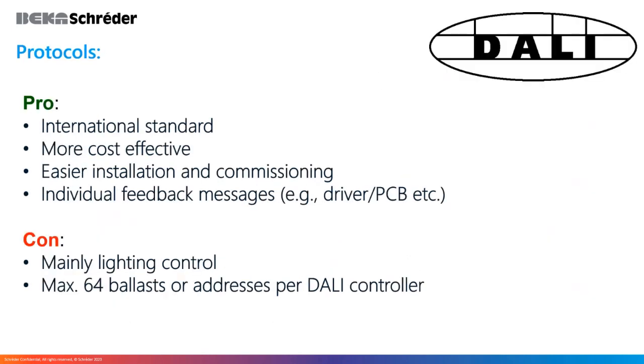Just some general pros and cons. Again, international standard. It's a more cost-effective protocol that you can incorporate into your units for, as I said, a future-proof, easy installation and commissioning in general. And then obviously you get the individual feedback and communication, the two-way communication. It's mainly a lighting control, and you are limited to 64 ballast or control gear per DALI controller.